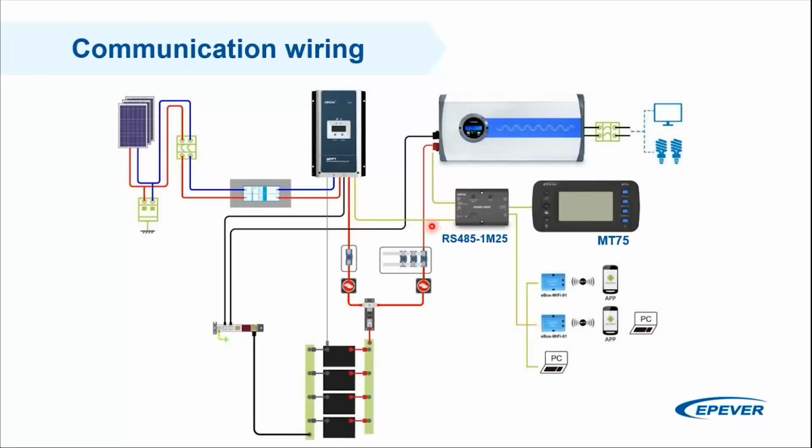So these cables are not carrying a lot of amperes or voltage. They are just signal lines. And the protocol is Modbus. So Modbus is a 2-wire or arguably 3-wire communication system. We have lots of slaves in our network and one master that is collecting the information from all of them. And the data is being transmitted by altering the voltage between these wires.